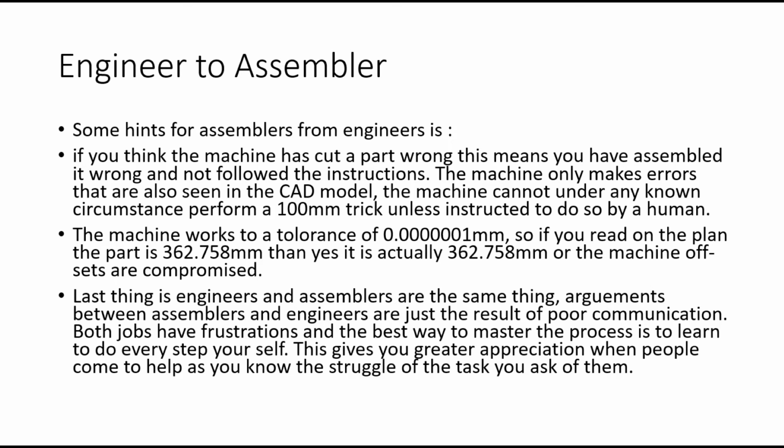Now if we have 16 gables between one wall and another wall and we don't take that 0.3 into the equation, then we have an accumulation of 0.3 by 16. At the end of this run of cabinets you get a gap of like 10 mil. It did not fit to the required measurements, and now the assembler will have to make fudges and adjustments on site to try to fix that.